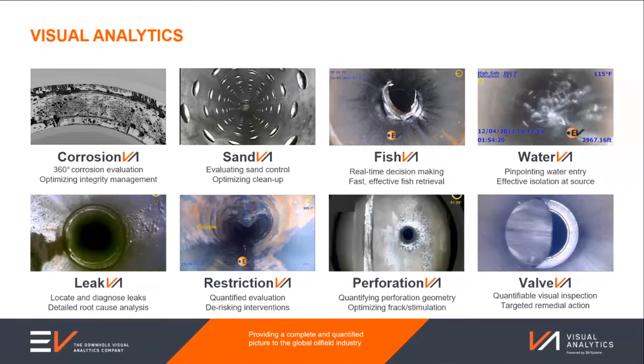Oh, I think actually I did leave one a little short. There was a question about the operating temperatures and pressures. So most of our camera systems are rated to 125 degrees Celsius, but we actually have variants of them that we can equip up to 200 degrees Celsius. Those are used quite frequently in HPHT wells, or sometimes even in geothermal applications. So yeah, there's a lot that we can do there.